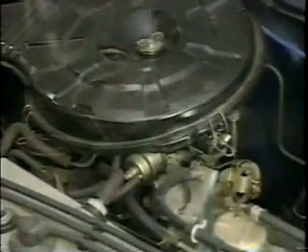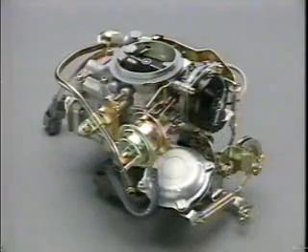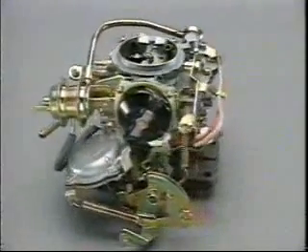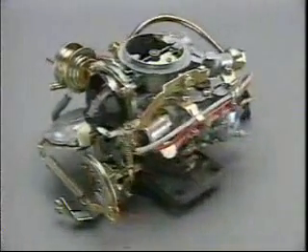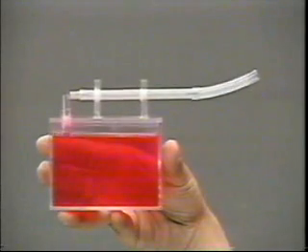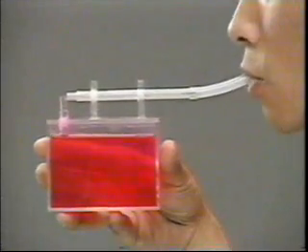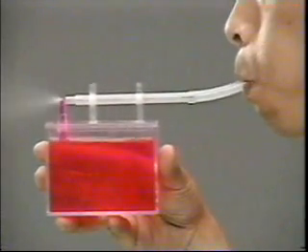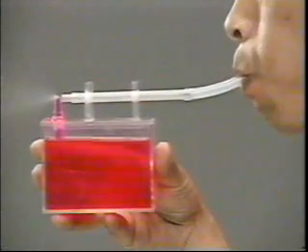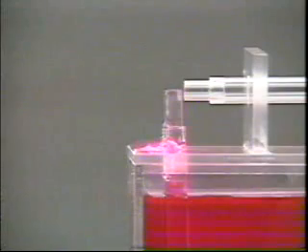The carburetor mixes the proper amount of air and fuel in accordance with the operating conditions of the engine and sends it to the combustion chamber. The principle behind this is similar to that of a manual paint sprayer. When air is blown through the pipe, the liquid inside is drawn up and mixed with the air, forming a spray. An increase in the speed of the air blown through the tube will draw up the liquid and create a mist.